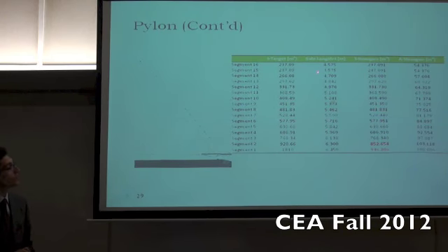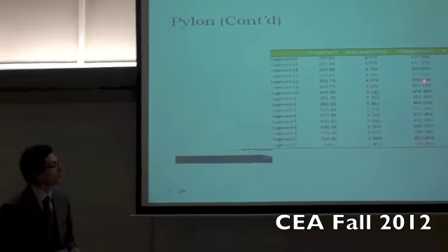And we use the Solver add-in option in the cell in order to calculate the equivalent side length, which will eventually get the same value of the moment of inertia. So you see here, this is the target, which is the moment of inertia of the actual pylon, and this is the hexagonal or the calculated mean value.